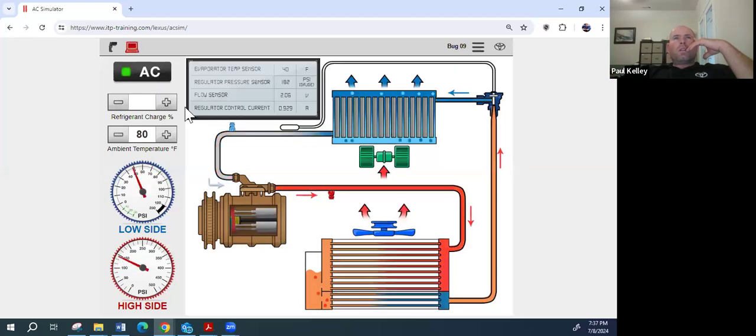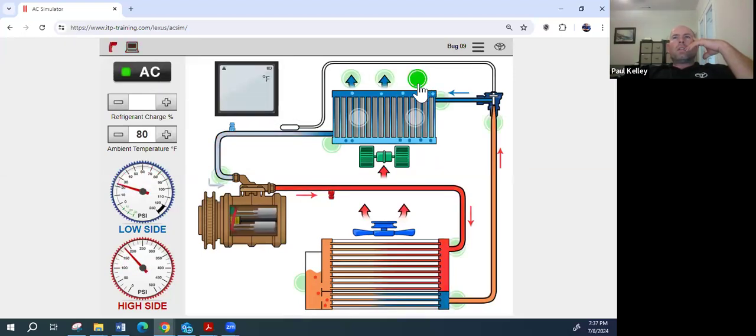Jump in the car, turn the AC on, check it. Blowing 45, that's all you could ask for, really, because that's the thing, it's humid there. The AC doesn't work as well when it's humid there. 45 on an 80-degree day would not be great for Southern California. But 45 in high humidity on 80 degrees, I don't know if I really object. But what was the concern again?